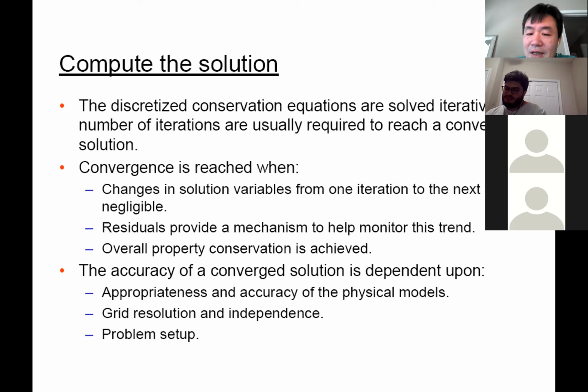it takes longer for the computer to run. Think about it. Every time step, the computer needs to run the equation for every grid point. If you put 1 million grid points there, every time step, it will run 1 million calculations. So in an unsteady simulation, you might run thousands of time steps, or maybe you run iterations to get the solution to converge, so you have to run hundreds of thousands of iterations. Every iteration you need to run the calculation on every grid point. It's very costly, very expensive in terms of time.